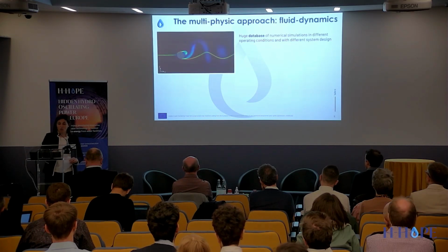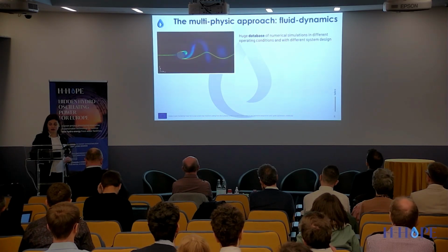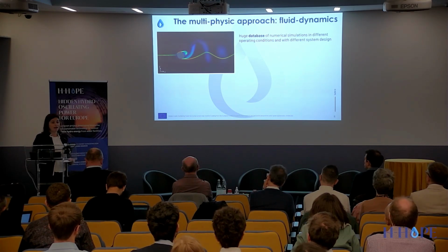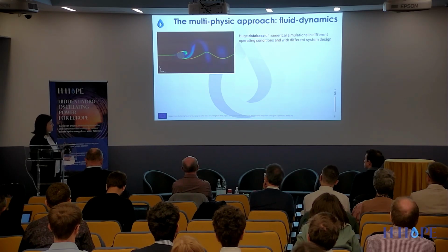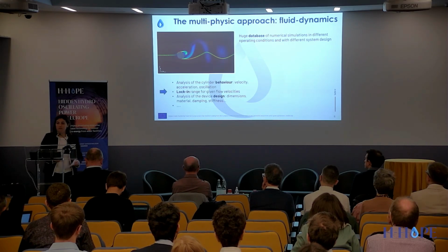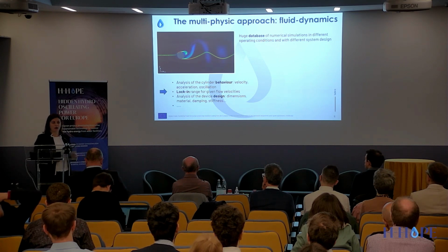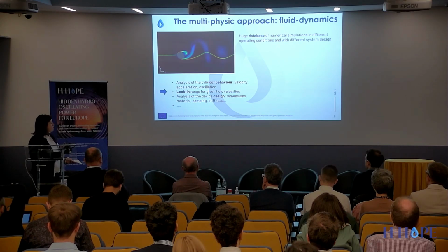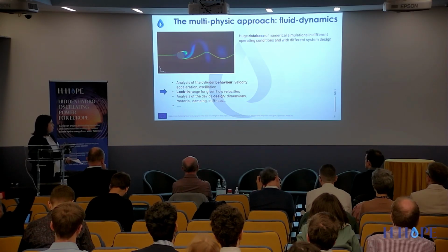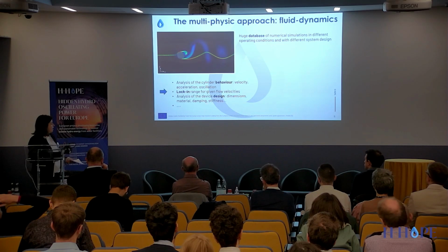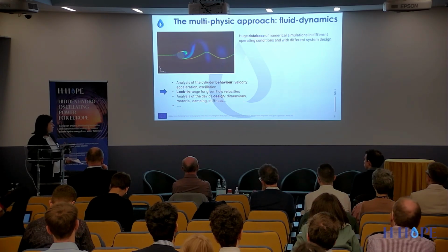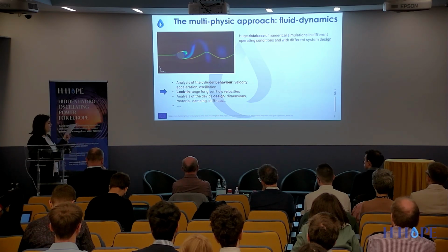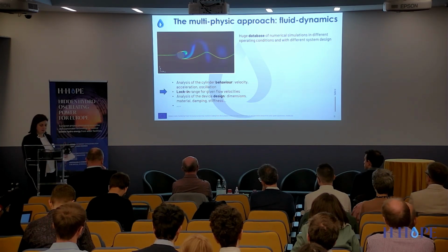To do this, we have done a really huge number of numerical simulations in order to create a database telling us how the body behaves inside the fluid flow. This has provided us quite some insight on the possibility of creating oscillation in the body, on achieving the lock-in condition, and on the factors affecting this lock-in condition: the dimension of the cylinder, the material that has to be used, the damping effect, the stiffness of the system, and so on.